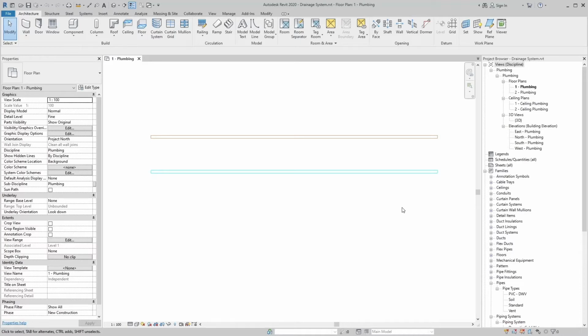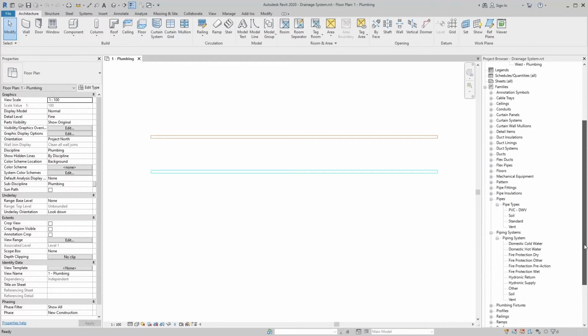While drawing pipes, we need some pipe fittings in specific sizes, for example, elbow, T, cross, flange and end cap, etc. The settings of these fittings are called routing preferences.